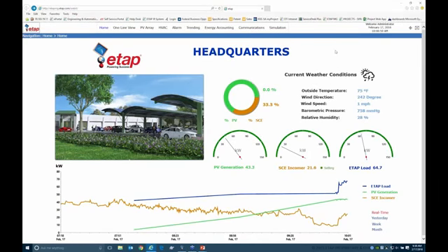and let's take an example of right now, and let's see what we get from our simulation. So what we're seeing right now is an actual view into what's happening in the PV system. We're actually producing about 43 kilowatts or so, and the power that we're buying from the utility is about 20 kilowatts. Our load is about 65.